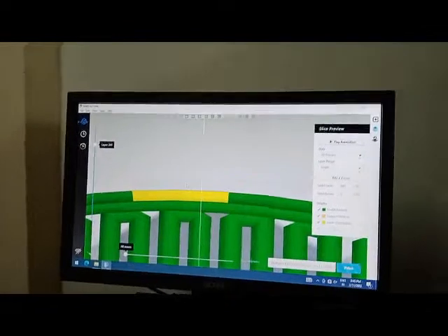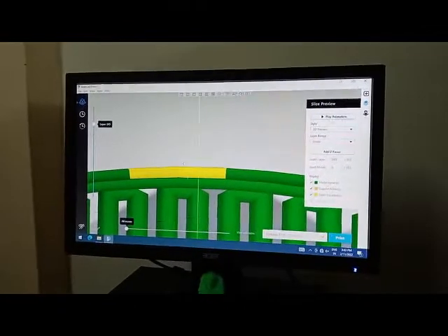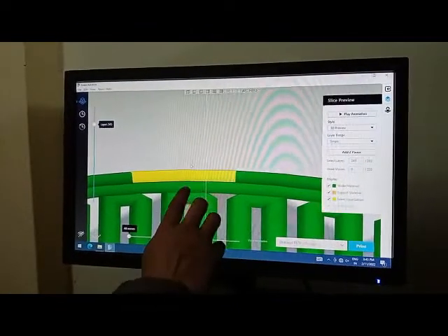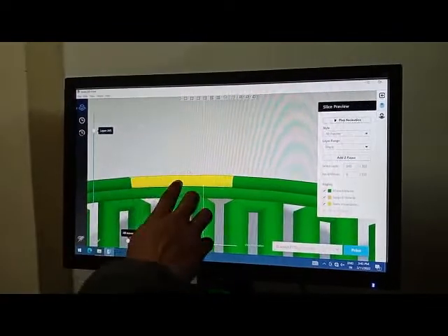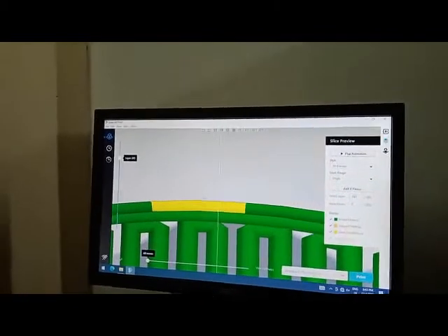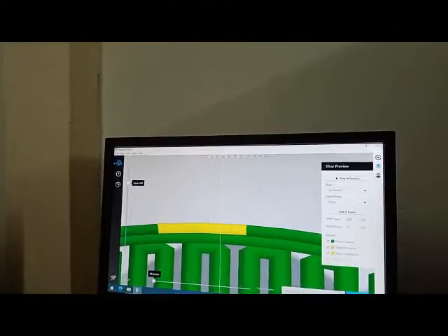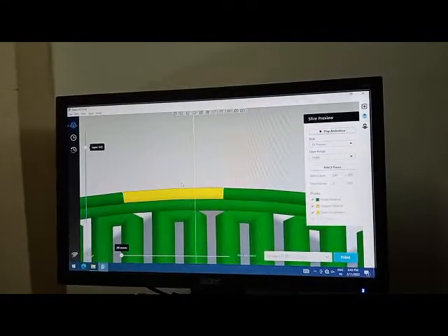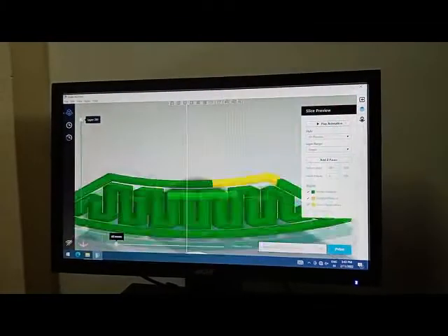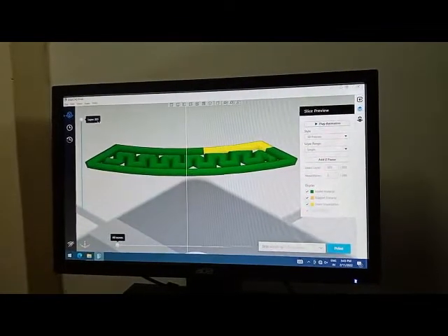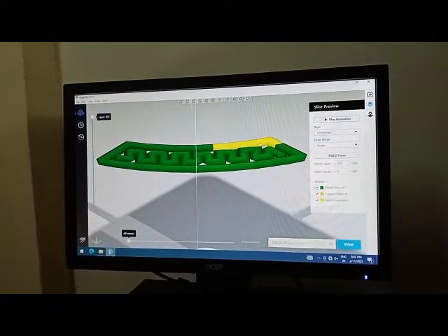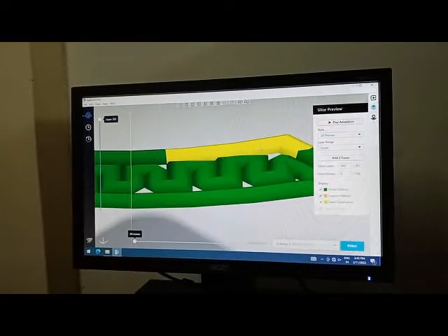Now why it is given is that sometimes in a part, when we finally print the part, the seam line will continue up to the final layer and we may have a straight line or some kind of impression. Currently I don't have any model, so I can't show you. Suppose the total is 303 layers in our part, in our geometry. So the seam will continue.